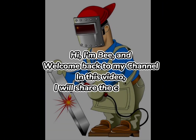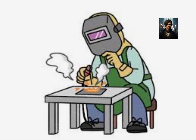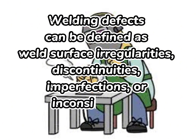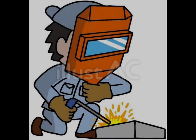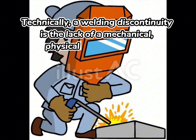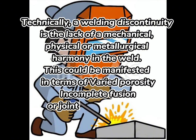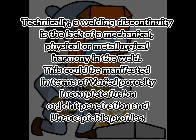In this video, I will share the common welding defects and their remedies. Welding defects can be defined as weld surface irregularities, discontinuities, imperfections, or inconsistencies that occur in welded parts. Technically, a welding discontinuity is the lack of a mechanical, physical, or metallurgical harmony in the weld. This could be manifested in terms of varied porosity, incomplete fusion, or joint penetration, and unacceptable profiles.